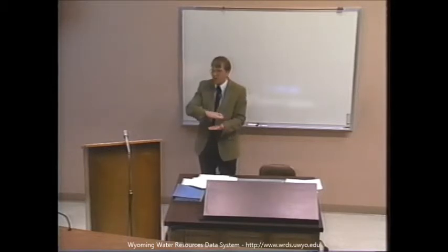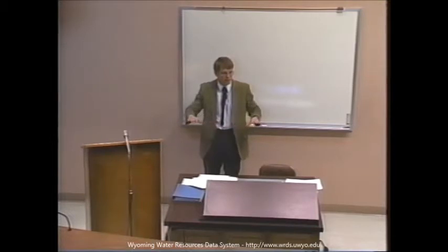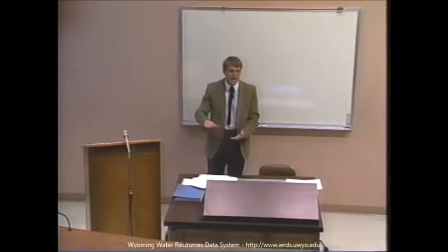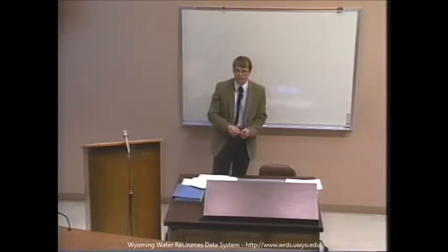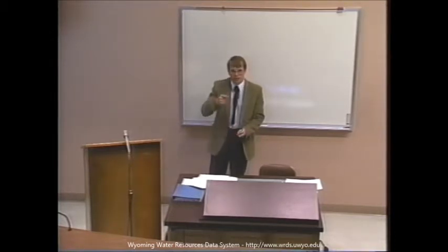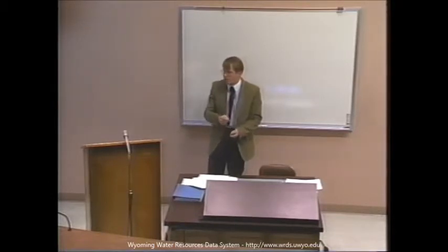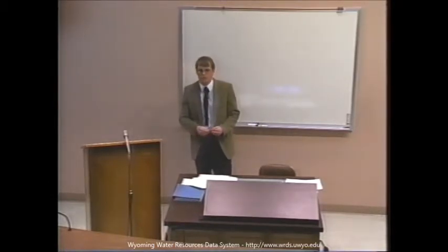Typically, an aquifer is layered horizontally with the properties fairly constant in that horizontal layer, and it is very nice to have a fairly accurate representation of the head on that layer. What does change, however, as you go in elevation throughout the aquifer, or a multi-aquifer system, is the conductivity, so you need that flexibility. Using the finite element in the elevation, you're able to incorporate that into your problem.